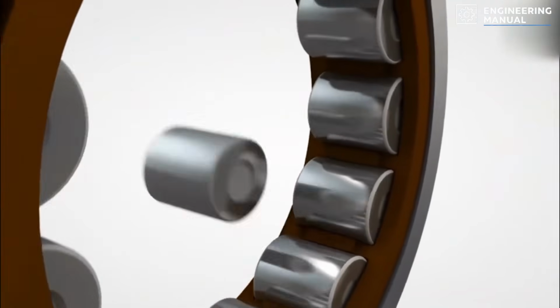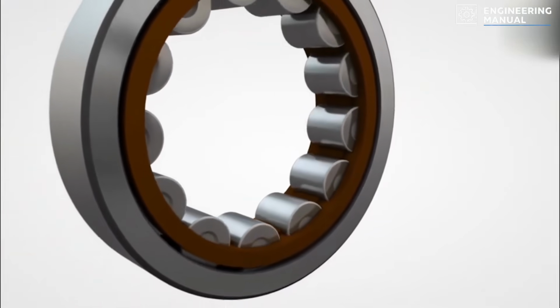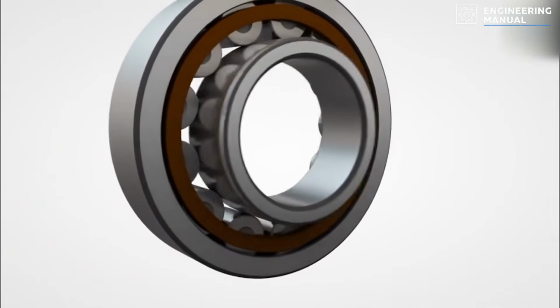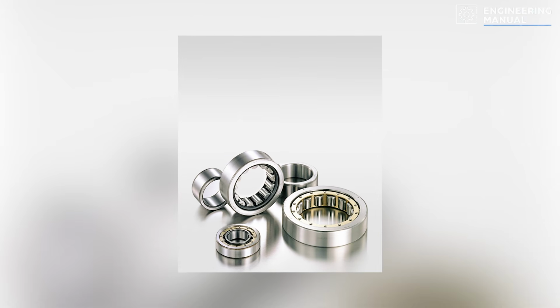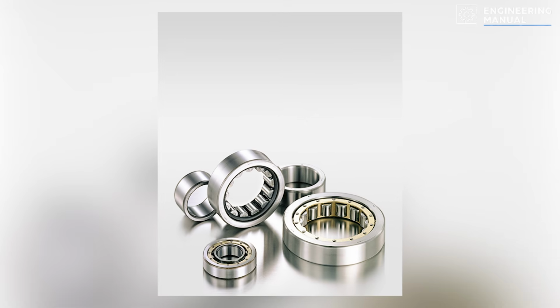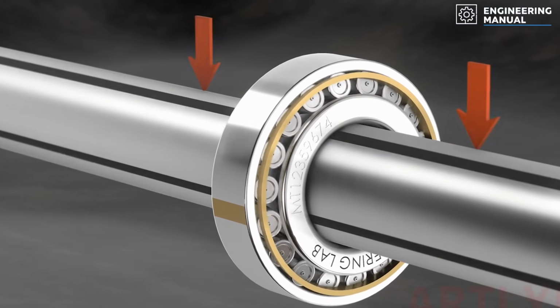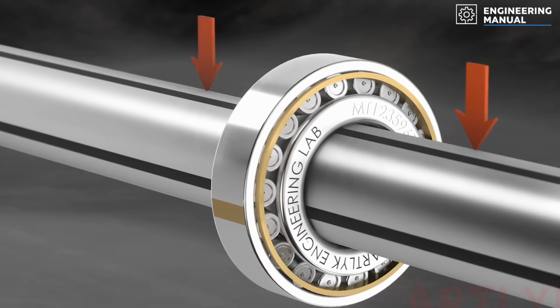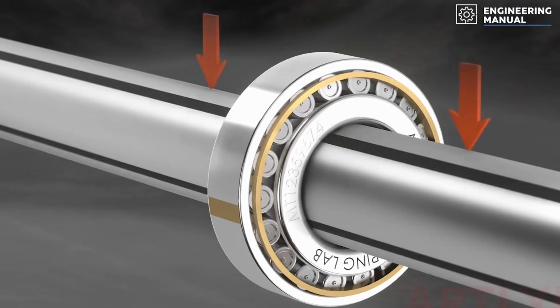Nothing else changes, the bearing still rolls, the shaft still rotates, but the same load is now distributed over a much larger contact area. Contact stress drops dramatically, load capacity increases dramatically. One simple geometric change fundamentally alters the bearing's capabilities. But once again, the new solution introduces a different problem.